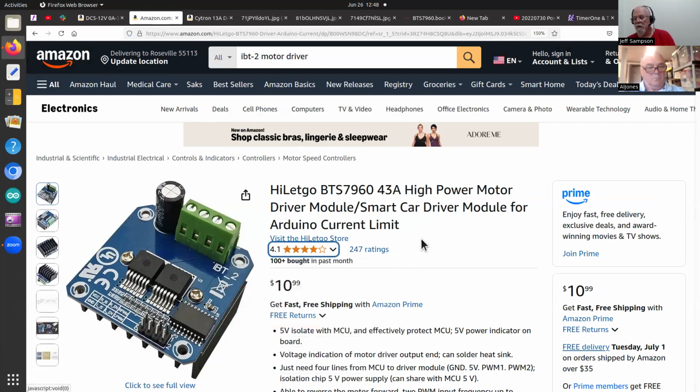So like Al just did, he's got one of the TimerOne processors, and to talk to this board, he defined 2 different output pins, and he's running the Arduino AnalogWrite command to generate a PWM. So he just says do an AnalogWrite on the first pin and it'll turn one direction, or you do the AnalogWrite on the other pin and that will turn it in the other direction. And it turns out that works because he only needs one board to do that. Well, actually it works because he's using the AnalogWrite. And we were discussing that before the meeting too.